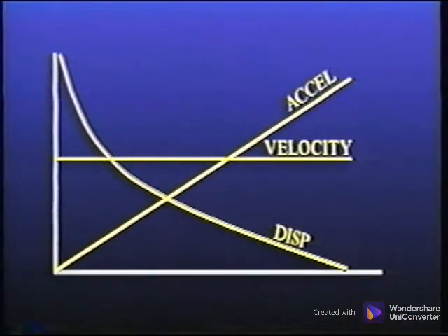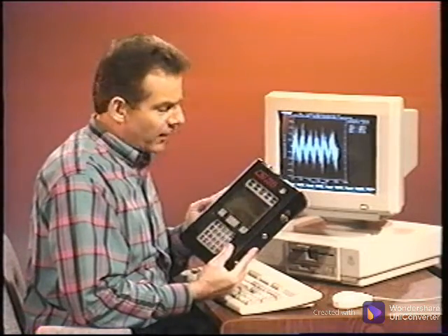As we develop the diagnosis for rolling element bearing defects in this program, we will derive tremendous value from acceleration time waveforms. Viewing data in acceleration clearly enhances the high frequencies, which is where the bearing defects occur. For these reasons, we strongly recommend storing the time waveforms in acceleration and the spectral data in velocity.